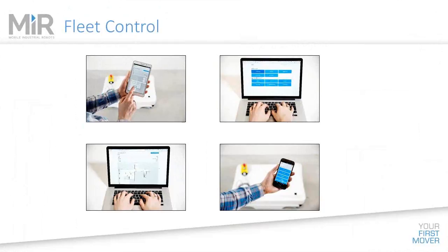Talk a moment about fleet control. Working on an application right now for a customer in the Cincinnati marketplace. That customer is moving work in process throughout the facility, and they're going to be using fleet control with a couple of the MiR robots with hooks. And at any given station, an operator will be able to select a particular mission, and it will be pushed to the robot that is the closest, or is the least busy, or has an adequate charge for the job. It does all the management behind that.